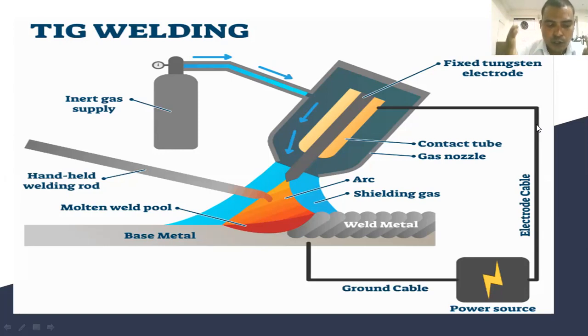It is also economical and heavier. So I repeat again why we are using argon. Argon is normally preferred over helium because it requires a lower arc voltage, easier arc starting, and provides a smooth arc action. It is also economical and heavier.